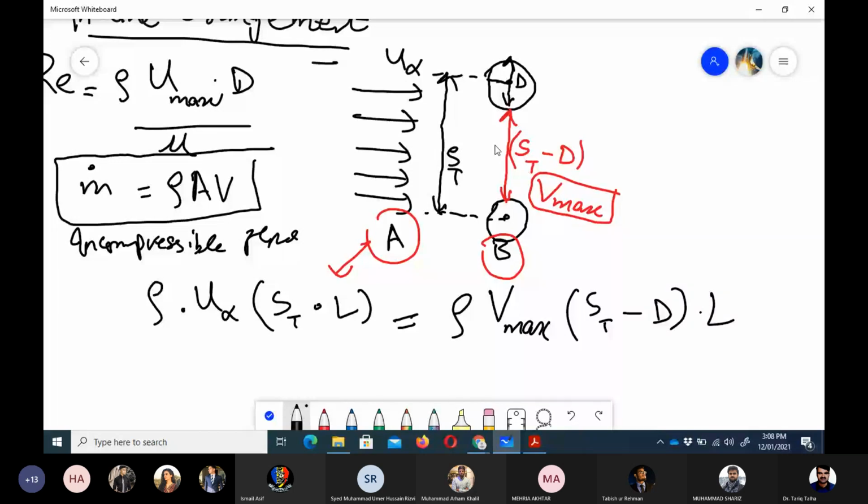There we would have the maximum velocity. As for the nozzle case, if we remember, the maximum velocity was at the throat of the nozzle, and then we can apply the convergent part as well to have supersonic flow here. So the nozzle is choked, which means that we would have sonic velocity here. That is the same effect. That is the throat of the nozzle.